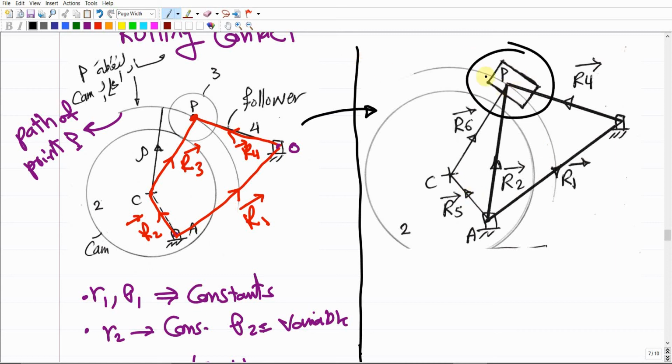There should be a roller here, and this is the point T, which is the center point of the roller. What we did here is replace the roller with a slider. And this is the point B, and this is the path over which point B is already moving. So in this case, we are just going to consider that we have a slider that slides over a link or over a curved path, like this case. Make sense? This is how it works for this mechanism.